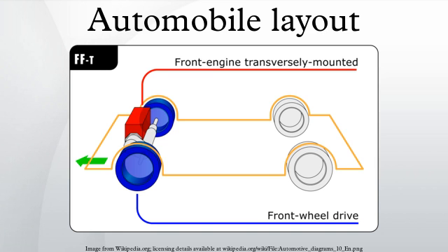Handling characteristics in normal conditions can be configured to emulate FWD or RWD, or some mixture, even to switch between these behaviors according to circumstance. However, at the limit of grip, a well-balanced 4WD configuration will not degenerate into either understeer or oversteer, but instead break traction of all four wheels at the same time into a four-wheel drift. Combined with modern electronic driving aids, this flexibility allows production car engineers a wide range of freedom in selecting handling characteristics that will allow a 4WD car to be driven more safely at higher speeds by inexpert motorists than 2WD designs.